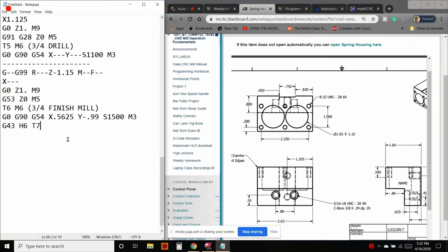Okay, and then anytime we want to call up a tool length offset, it's a good idea to move Z so you have a predictable Z movement. I've worked in a lot of different shops, and it seems like everywhere I go, people wrap it to an inch above the part. We're only allowed one M code per line with a Haas, so we want to take advantage of that and say M8. That way, if the coolant lines are kind of clogged on the way down, it'll give it plenty of time to turn the coolant on.